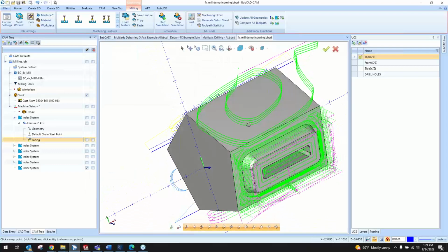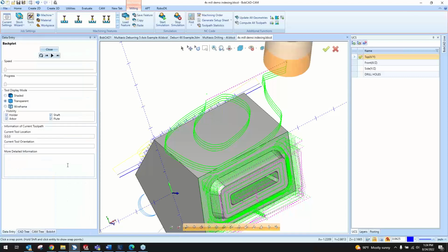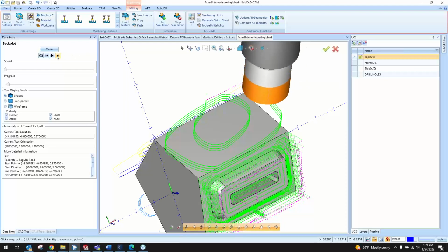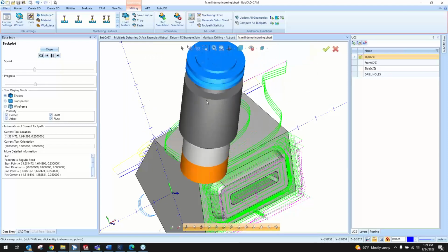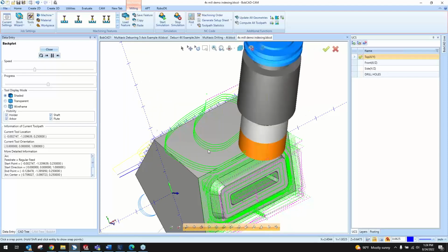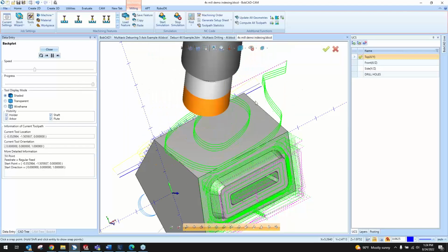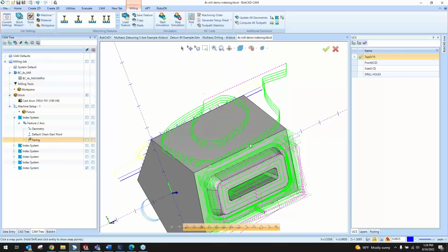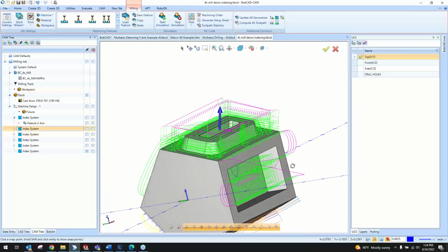We'll see the toolpath is a little different there. There's the adaptive toolpath instead of the zigzag that we had. We'll backplot that to see how it looks. Kind of step through, works its way from the outside of the stock, works its way in. And kind of does this spiral option, goes up and links to the next location there. And then from there, we'll index to the next surface around the part.